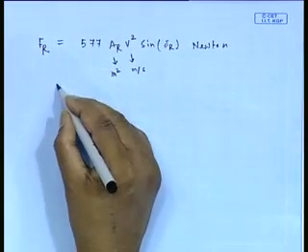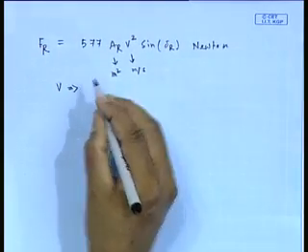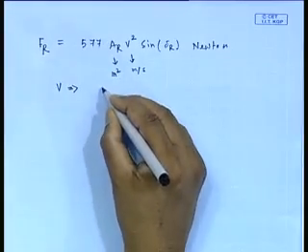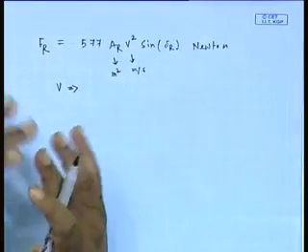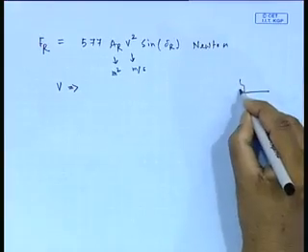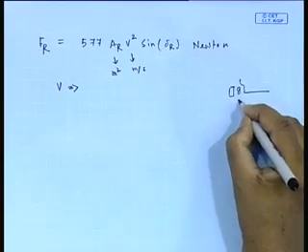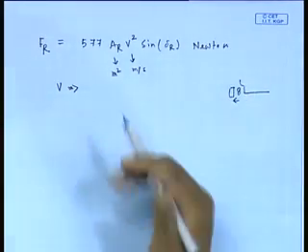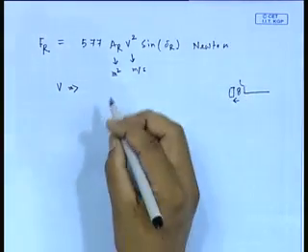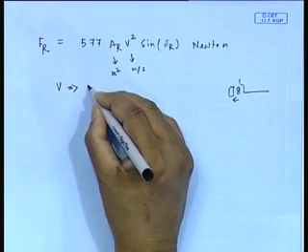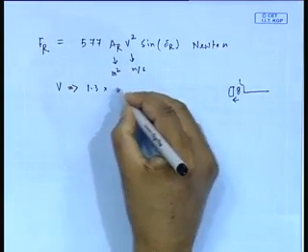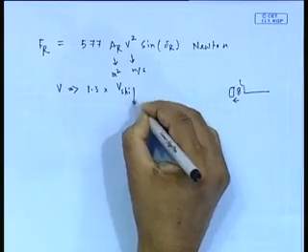When you do V, it should take into account the fact that the water flowing past the rudder is of higher speed because the propeller is racing it. The rudder will always be behind a propeller typically. So, the V that comes into the rudder is usually higher. So, in this formula one has to use V equal to 1.3 into V ship